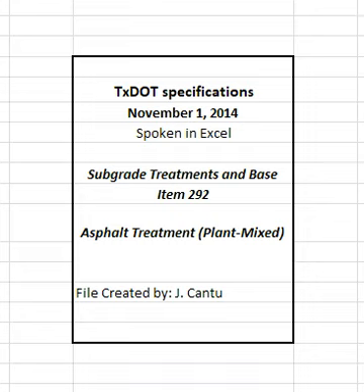4.6.3 Placement sampling and testing. Obtain 2 6-inch diameter cores side by side at locations selected by the engineer. Provide the engineer an opportunity to witness the coring operation and measure the core thickness. Mark the cores for identification.